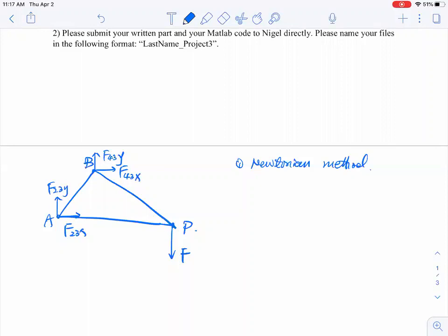That's relatively easy, right? The free body diagram. And then if you remember, we need to find the equations for link number 3. In the X direction, you just sum all the X components together, because your P point force is always vertical, so there's no horizontal component.